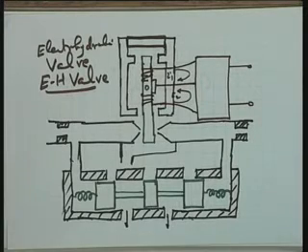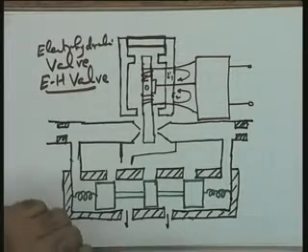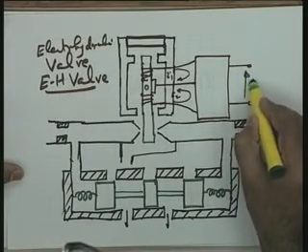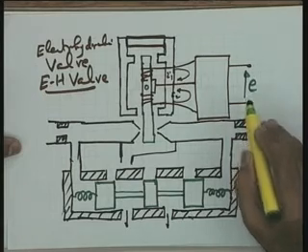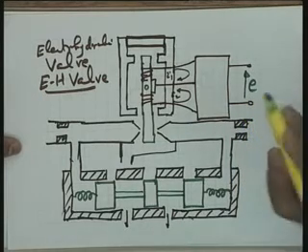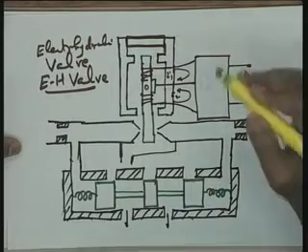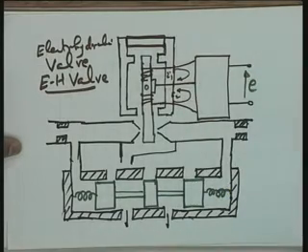Well, I hope you will understand this quickly, because once you have seen that motor, the action of this is not going to be difficult. This is your error E. Once I talk of an electrical controller, an electronic controller, the error is going to be a voltage variable or a current variable. So let me take E as the error. Keep in mind, error variable is a representation of the deviation between the command and the actual action.